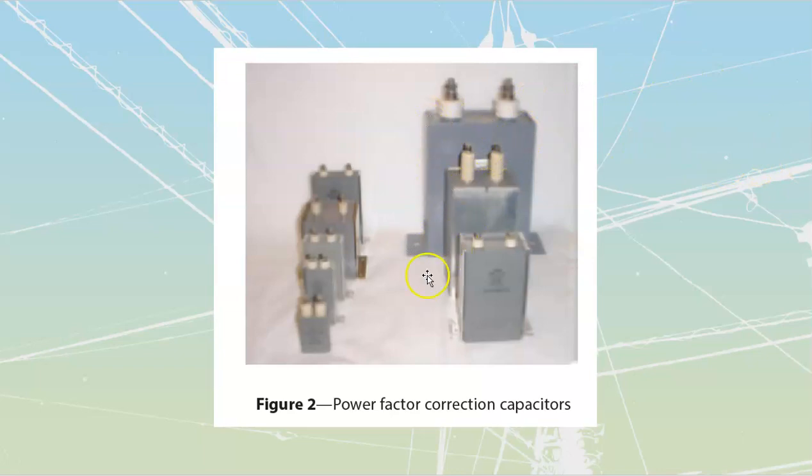This is what we refer to as an electrical bushing, and it's going to be a high voltage connection point onto these. These will be even on medium ones, just because of the way that they construct these things. You need to have some sort of a sturdy lug to mount onto these things. They do talk about how we should not exceed the ratings of them, the AC as well as the DC working voltage. We've calculated DC working voltages by taking our AC and taking it to a peak before. Make sure that whatever caps you're going to be utilizing are rated for that.